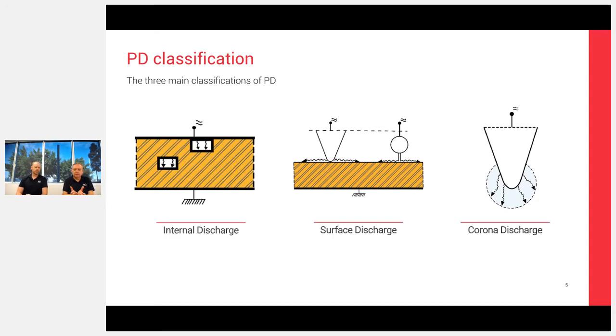is enclosed, and then what happens is the byproducts, nitrous oxides, generate nitric acid and start attacking the insulation, and then making surface discharge happen on that switchgear. So the two that we particularly concentrate on are internal discharge and surface discharge.